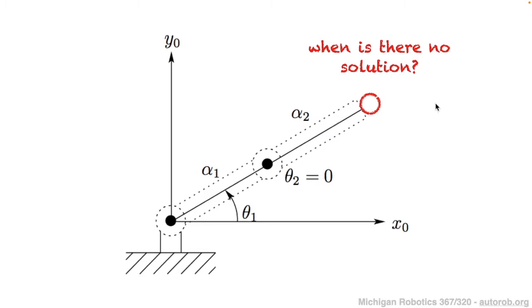Another interesting case then is to ask, would there ever be a situation where we could input some desired end effector position and there is no solution produced by our inverse kinematics routine? And the answer to that is actually yes. There are cases where for our inverse kinematics routine there will not be a defined solution. In particular, if we position the end effector such that based on the pendulum lengths, they could never reach this end effector position. And so this is one thing to think about when we think about inverse kinematics routines, is that we are trying to solve a constrained set of equations by basically modifying a set of variables that are unknown. Anytime that comes up, the number of unknowns and the number of constraints that we have are going to determine whether the system is overdetermined or underdetermined, which can again affect whether or not there are unique solutions or no solutions to the actual system.